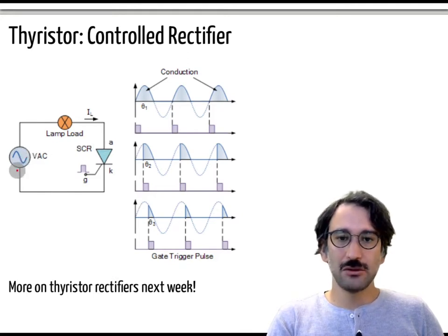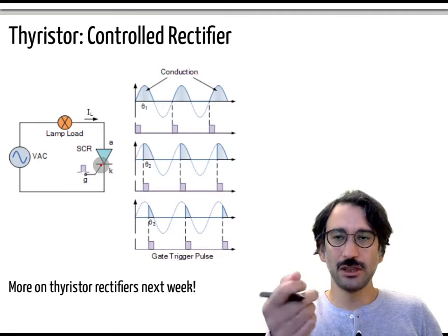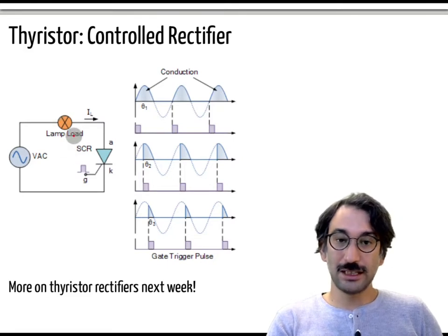But let's say you connect an AC voltage source, and you can have an RL load like a lamp or that kind of thing, and actually thyristors can be used in that kind of dimmer switches that you can adjust the lighting. So if you have a circuit like that, normally you have a waveform like that, and if it were just a diode, you will have just the positive cycles like that. However, here is your gate signal. If you just apply the gate signal at that instant, it will just start conducting like a diode.